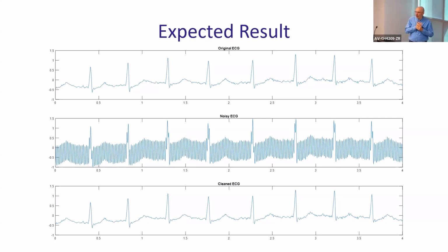So what would be the projection operator directly to the signal space now instead of the noise space? If you take sine and cosine as columns of matrix A, then you will get projection to the subspace of noise. Okay, so you'll have only the noise component, which is only a 60 Hertz sinusoidal wave with particular amplitude and phase. But what would be the projection operator that you can get for the signal out of that? What should it be? And as I said, the signal is just the original Y, which is the noisy signal, minus noise.